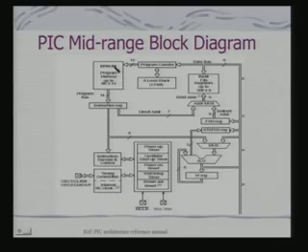Here, let us see, this is my program memory. This program memory is obviously distinct from that of my data memory. The data memory is located here. So, this is an example of Harvard architecture. I have got this program counter, and program counter is obviously generating addresses for my program memory for execution of